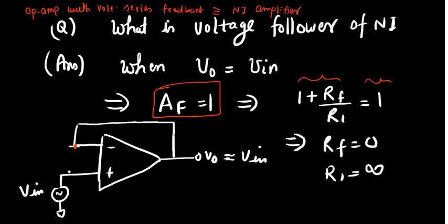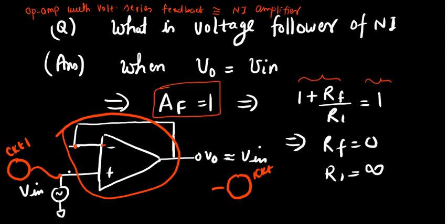See, there is a circuit here, from where you are getting some output. And here you want to cascade these two circuits for some application. But when you feed this output to the input of this without using an op-amp, it will not be isolated, right? Because this input resistance is very high. So this is a block, correct? This will work as a block which will isolate these two entities.